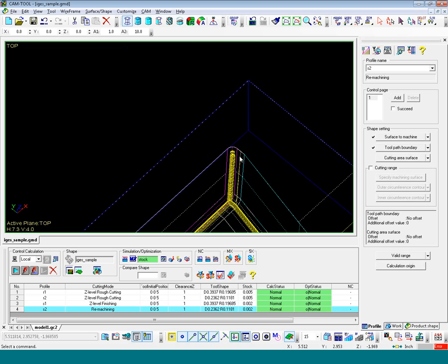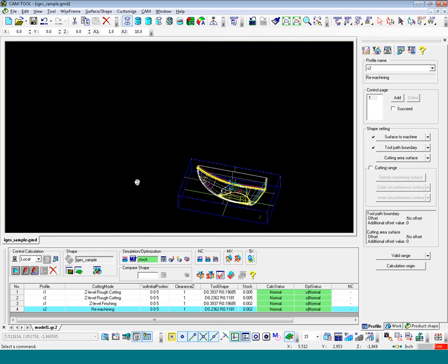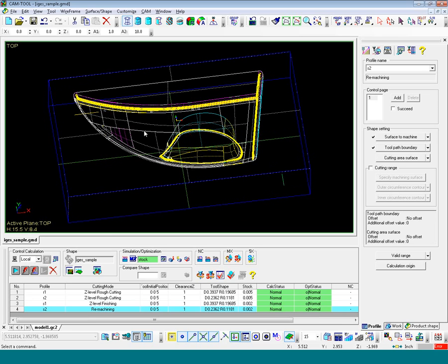Very important to use the remain step when a tool hasn't been into that particular corner yet. Once it's been in, then you only have a little bit of stock left, so it's okay to remove that remain step so that your tool path runs a little faster.